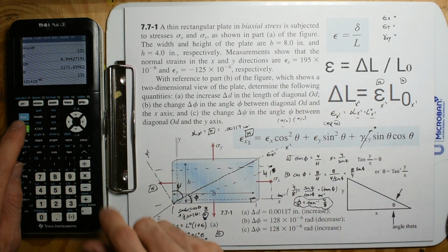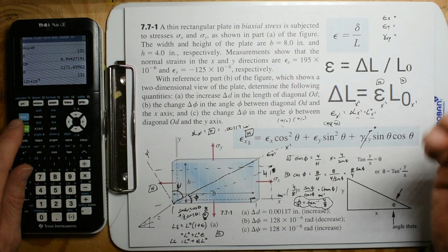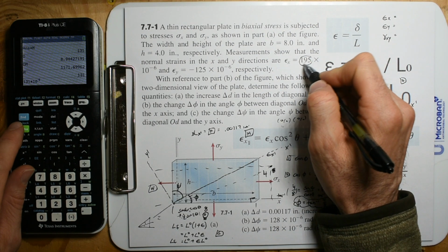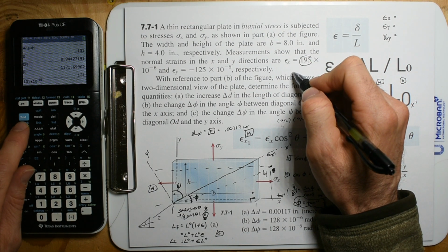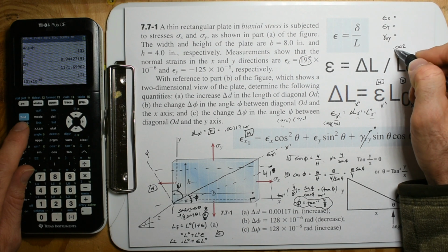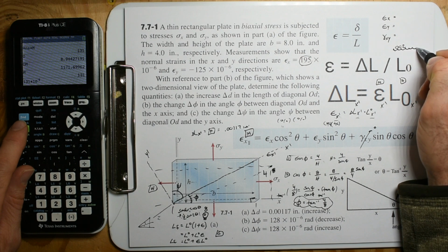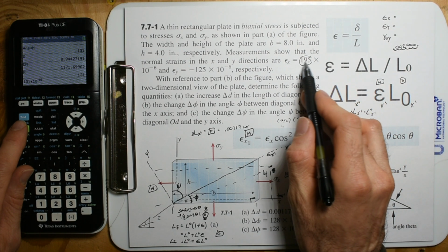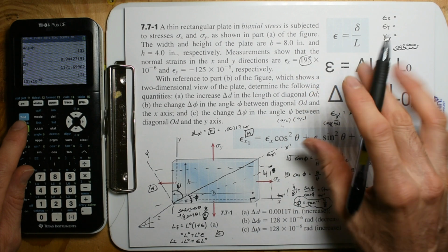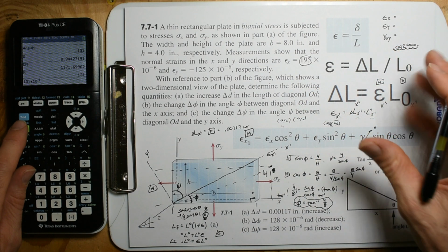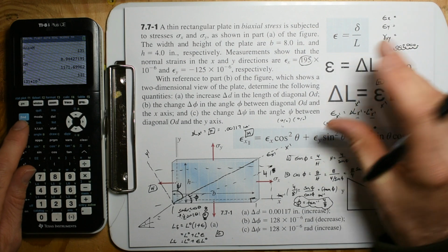I just multiplied by 10 to the 6 to show you that when dealing with strain, you're going to be in this ballpark of hundreds or thousands. Because 0.002 for steel, move the decimal place 6 times: 1, 2, 3, 4, 5, 6. That's going to be a value of 2,000. So your strain values are going to be between like 10, 20 to 2,000.